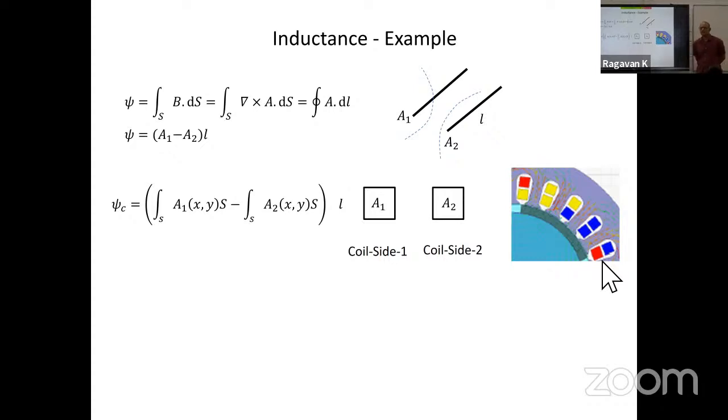Okay, think about what happens if you have done the same thing in a lab. I gave you an induction motor and an LCR meter. So the measured terminal inductance, is it the total inductance of the winding? I'm asking about the phase A winding, not the rotor side inductance or the rotor bar inductance. I'm simply asking about the stator winding inductance.